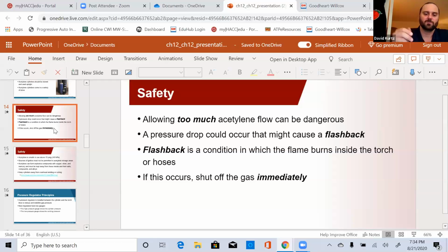So if you take your welding tip and actually drop it onto your base metal and the flame goes out, then you're going to hear a pop. A flashback, some kind of debris came up through the hole at the end of your welding tip, and it's going to sound more like a machine gun. You're going to get pop, pop, pop, pop, or like a high-pitched shrilling sound. Like I can't do it right now. Anytime you hear that, take your needle valve, shut them off.